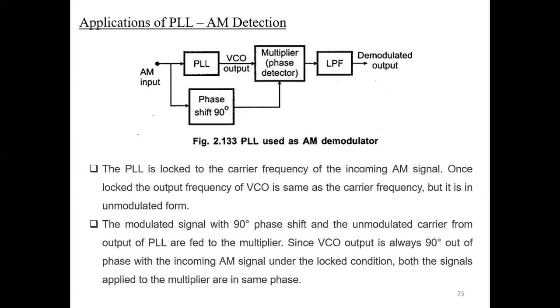FM, you have to move to that 98.3. So the input frequency and the voltage controlled oscillator frequency will be matched with the 98.3. Then only the signal will be received. So this concept is applied in most demodulation processes. So the PLL is mainly used in demodulation concepts.